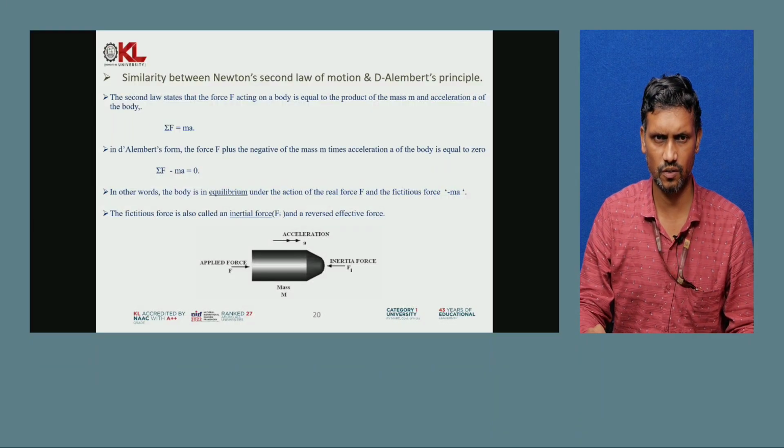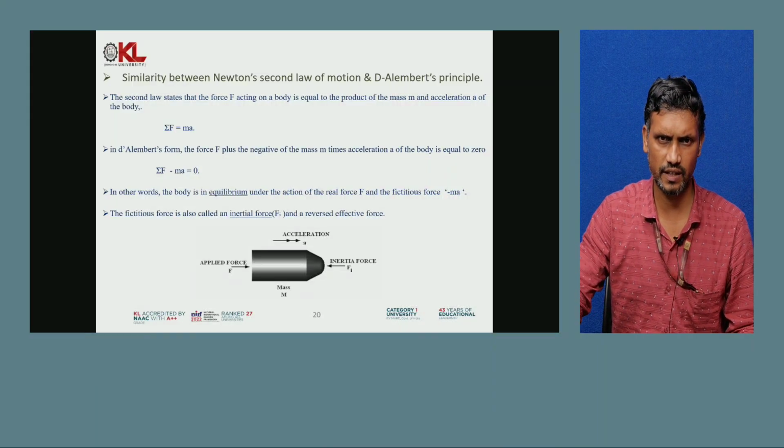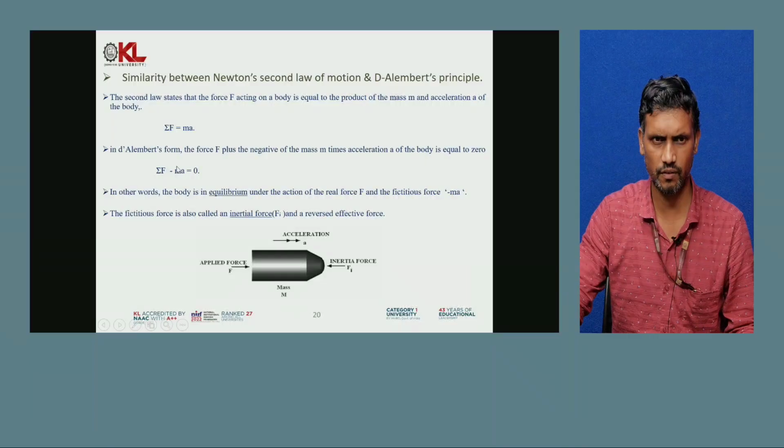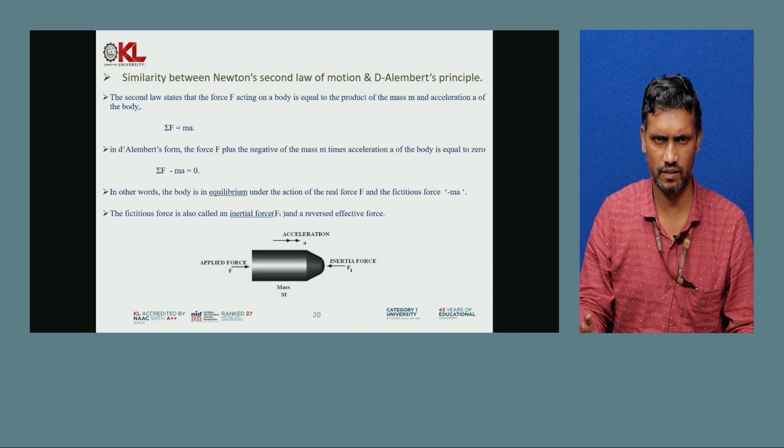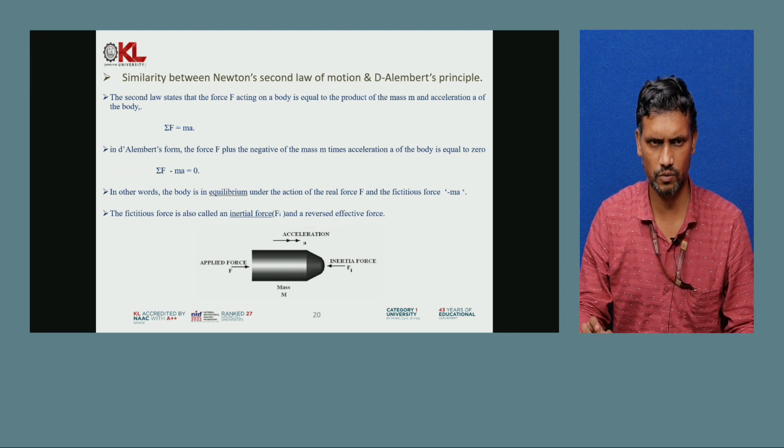Now, similarity between second law of motion and D'Alembert principle. As I told you just now, summation of F equals ma, summation of F minus ma equals 0. In the second law there was the product of mass and acceleration which equals force, but here force you are subtracting with m into a and equating it with 0. So almost the same, you are just transferring one thing from one place to another.